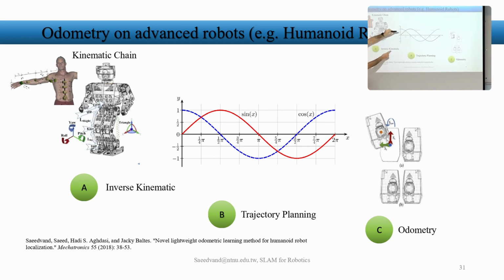Because I have inverse kinematics, I can send the position, and if I generate this part of the sine and the robot foot follows this, then I'm generating this trajectory. And the other foot can be on cosine, for example, on a movement like this.